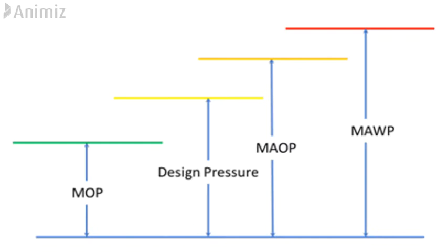Design pressure is less than or equal to maximum allowable working pressure. When MAWP value for a fabricated vessel is not available, design pressure value should be used as a conservative replacement for MAWP.